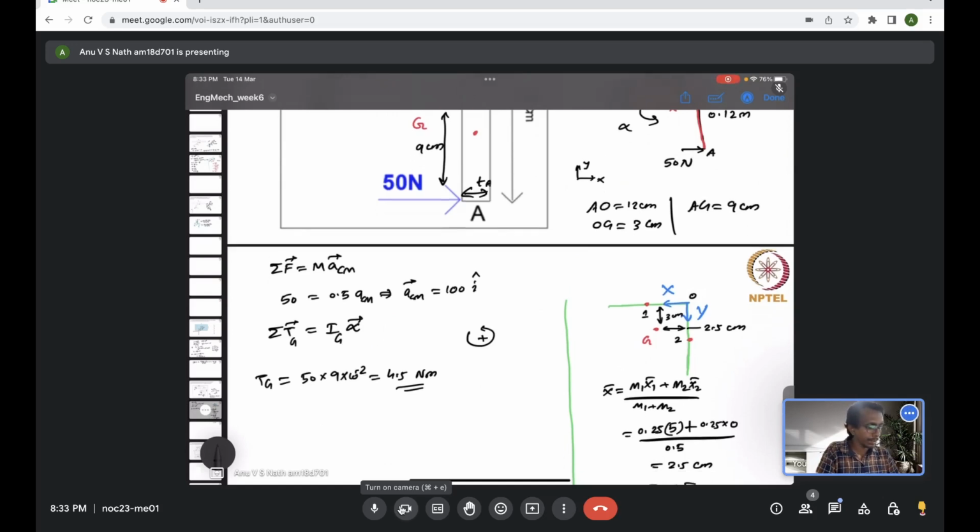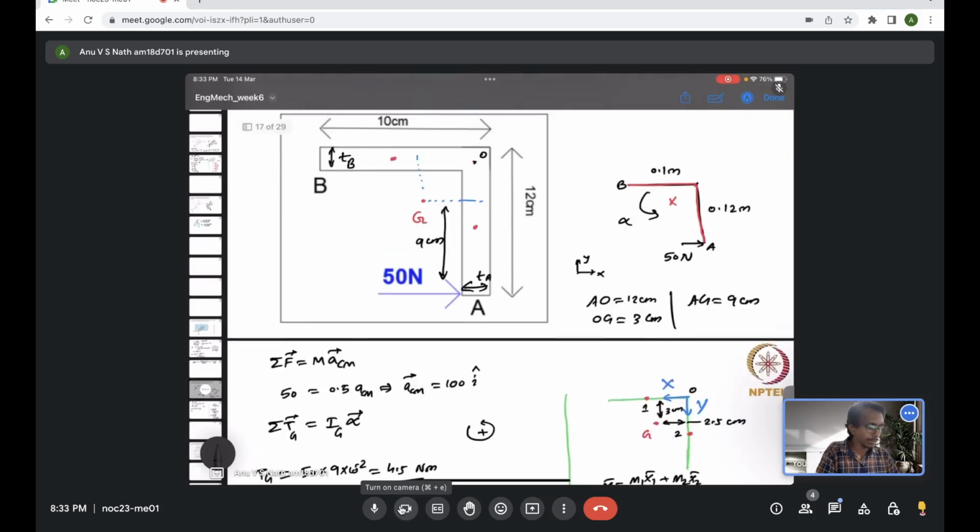Okay. Now I about G needs to be evaluated. So moment of inertia about G. Now we have two rods actually. One arm is A and another arm is B. So moment of inertia due to both needs to be considered about the center of mass G. Now let's denote the center of each of them. Let me call this C and this D, which is the center of each of the rods.